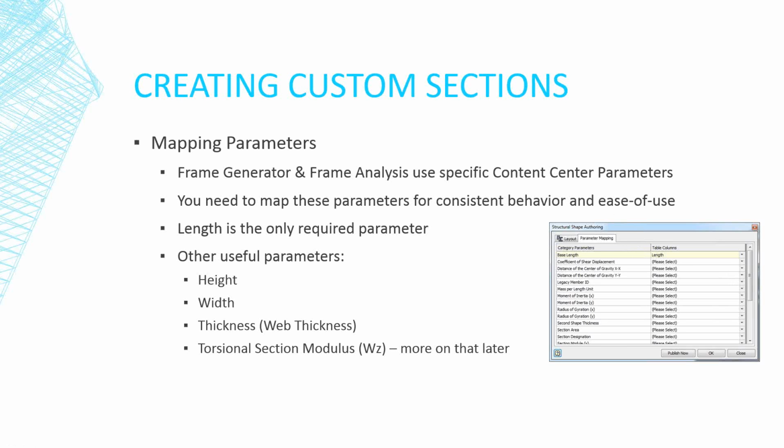But especially if the shape you've drawn is maybe simplified, you may need to override whatever Inventor might calculate with these values. And so you'll ultimately need parameters, either model parameters or columns in your iPart table. That's why it can be important to convert this thing into an iPart, even if there's only a single size, because you'll want to map iPart table columns to these various category parameters.